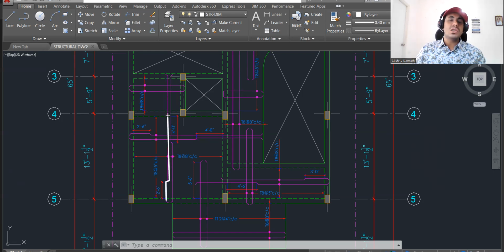No, I could have stopped it here also, but I have this much small portion, so I'll go like this. Finish. Next, what have they done? Yeah. Next, he has started the bar from here. It's a continuous support. So what you'll do, you'll give a crank and you'll take it to the top like this. Got it? So in this way, the reinforcement has to be provided.